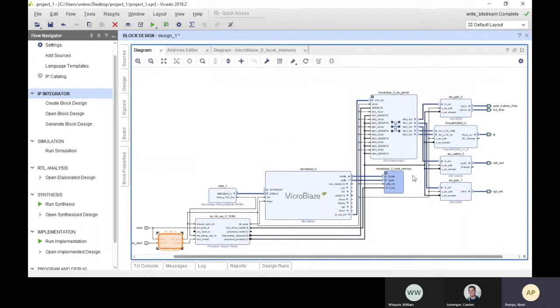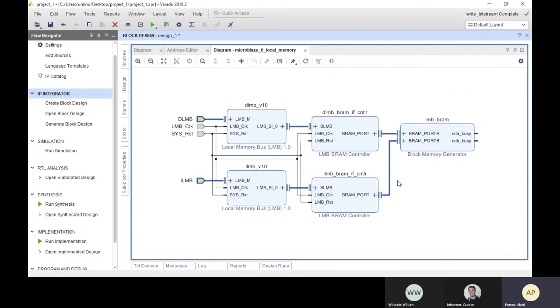Also, we can look through these different modules. You can click on these modules, and as you build them, there are more parameters. They're pretty self-explanatory, but as you can see, sometimes there are other modules that live within this. It's almost like when you're building your VHDL code and you have a top module, and then you have submodules that live underneath that. That's the same thing that we're looking at over here. And this is all the RAM, how the RAM is composed right here, from local memory to BRAM to our block memory. So we'll close this up.